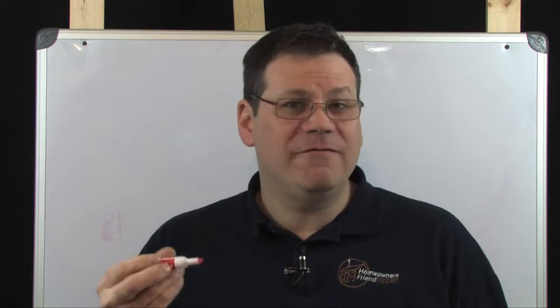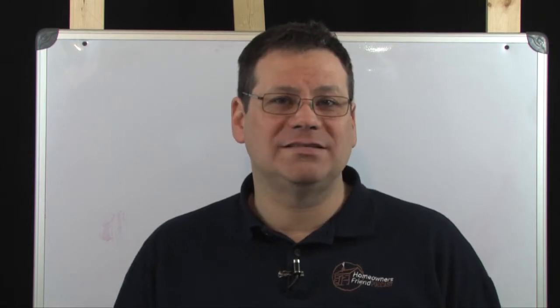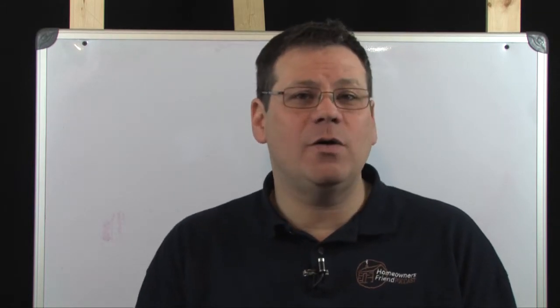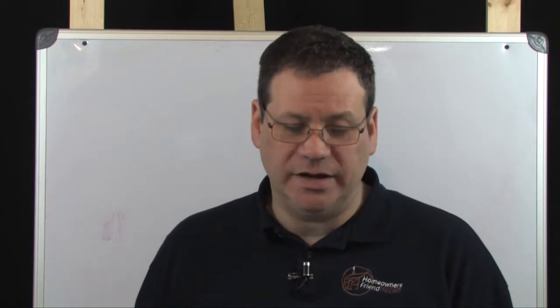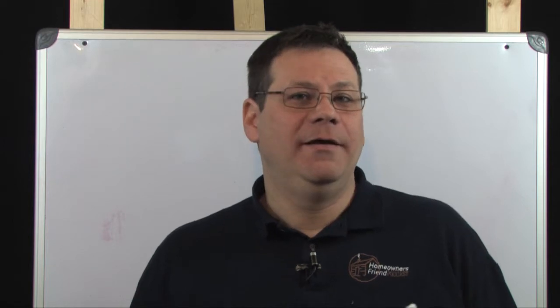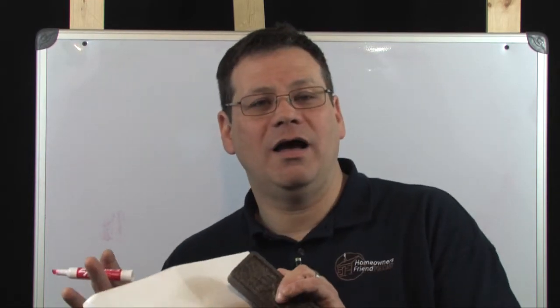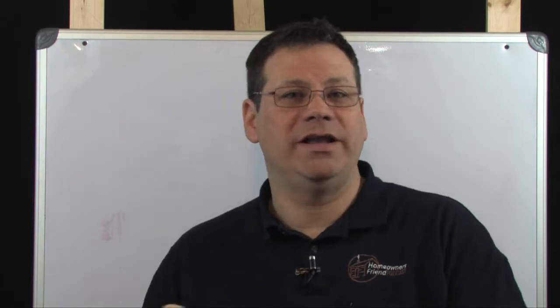And it goes the other way as well. If the thing only used 50 watts and I ran it for 2 hours, that would be 100 watt hours. Or 10 watts. If it used 10 watts of power and I ran it for 10 hours, that would be 100 watt hours of electricity, and so on. So you can see that it's not only how much it's drawn, but it's how long it's being drawn for, and you have to know both of those things to be able to calculate it.